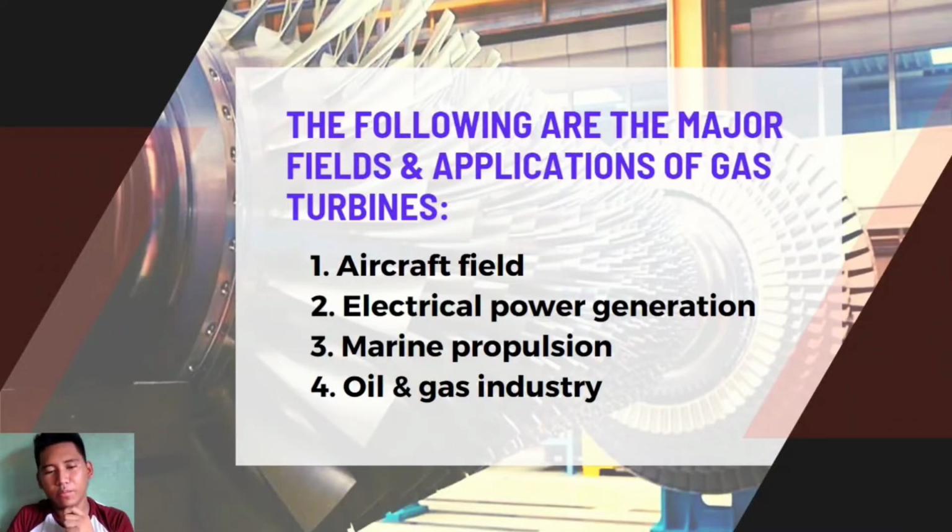In electrical power generation, even though the initial cost of a gas turbine is less than either alternative for moderately sized units, its inherent efficiency is also lower. Yet a gas turbine unit requires less space and it can be placed online within minutes, as opposed to a steam unit that requires many hours for startup. As a consequence, gas turbine engines have been widely used as medium-sized peak load plants to run intermittently during short duration of high power demand on an electric system. In this case, initial cost rather than fuel charges become the prime consideration.